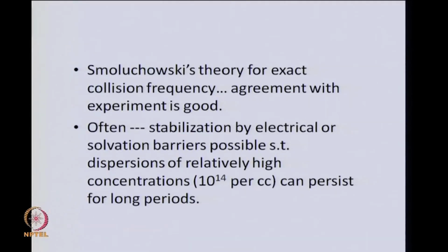No, I said there are two ways in which you can have the colloidal particles forming in condensation itself. In condensation, you could have one kind of system which is relatively rare, very pure system. There is only the supersaturated solution. It could be the water vapor in air free of dust particles, or it could be supersaturated solution in a crystallization system without any seed crystals or roughness on the surface, because those particles, if they are present, are sites of lower free energy. So, the system goes by relieving the supersaturation by depositing this solute, which may be the vapor or the solute in the supersaturated mother liquor. It is now deposited onto these particles.